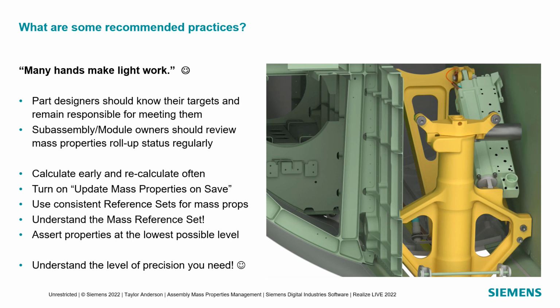If you're updating associative expressions for the parts, they're going to need to load more of the part than the minimal load. That's going to require a little heavier load, sometimes a lot heavier if you've got very, very large assemblies. So that's one to keep an eye on. Again, if you've got very large assemblies, you may avoid setting that customer default for associative expressions.